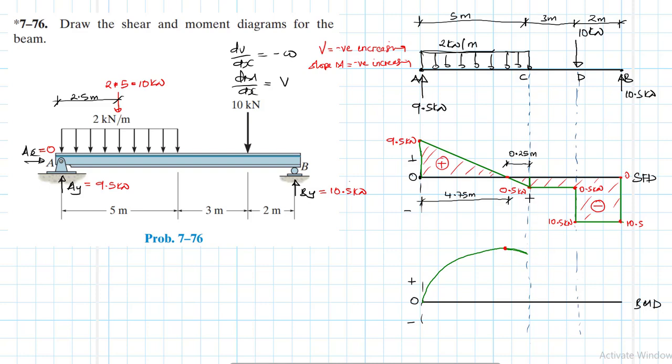Right. And then the moment we reach at D, the conditions change. What do we have at D? From C to D, the slope, I mean the shear. Shear, okay. The shear itself here is negative, okay, and constant, right?